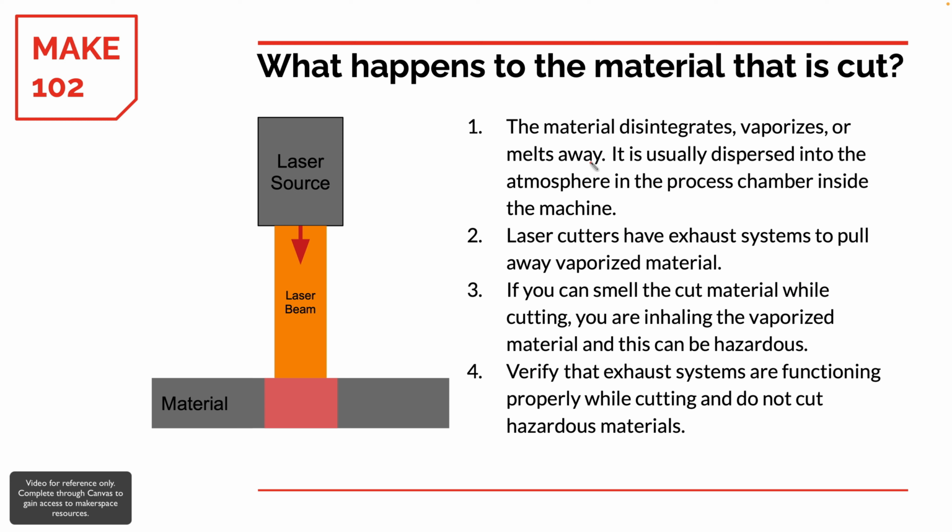So we want to make sure if we are smelling the cut, something may be wrong. We should not be smelling the cut when we are cutting with the laser. And we should also verify that we don't cut particularly hazardous materials, because no exhaust system is perfect, and we don't want to be inhaling hazardous material.